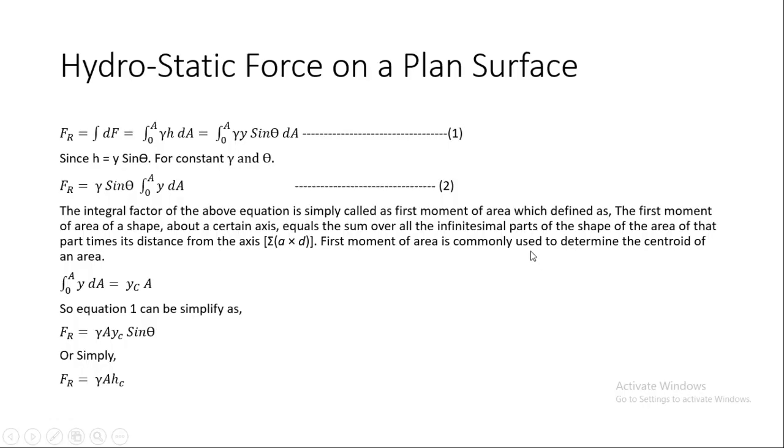Its definition is the sum of the infinitesimal parts of the area times the distance from the axis, which can be equated by definition to yc times the area.